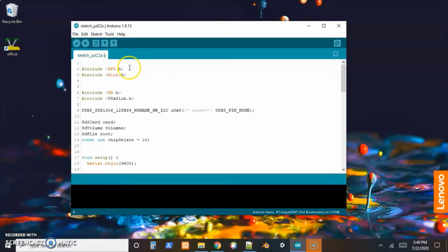Okay, so just a couple things to glance at in the code here. Like I mentioned, these are standard protocols, so there are already libraries pre-built and ready to go. So just bringing in the C++ library that has the standard SPI communication protocol set up for the Arduino, and same thing with the C++ library that has the standard I2C set up for the Arduino, built into the chip. Since, as I made the point earlier about it being big enough to work with, there's plenty of room, so they went ahead and wired up some pins for those.